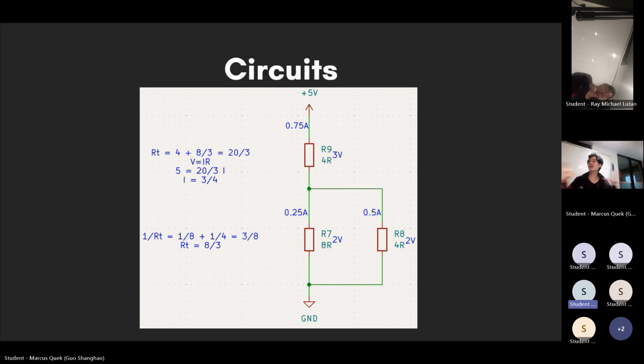That's right. We simplify the system by kind of compressing complicated areas into small parts. So we take this whole parallel system, we just treat the whole thing as one resistor. Then we can analyze the whole circuit, right? Okay, great. So we're doing things slowly and methodically, one little bit at a time. If you try to do the whole thing at once, you will cry.